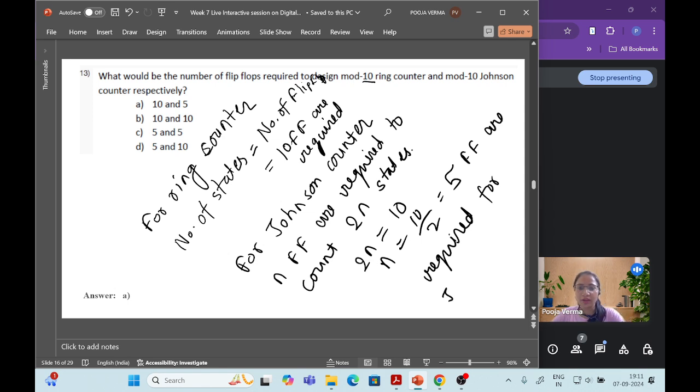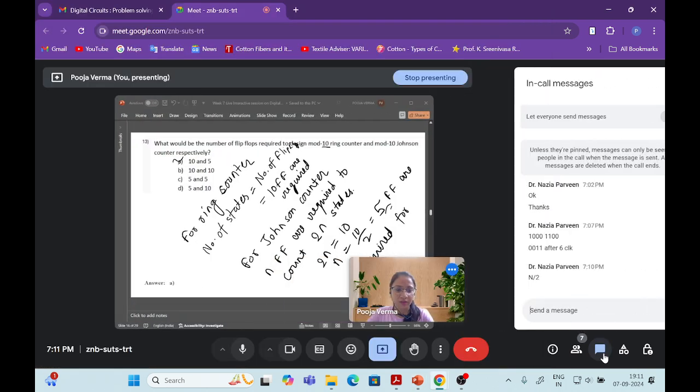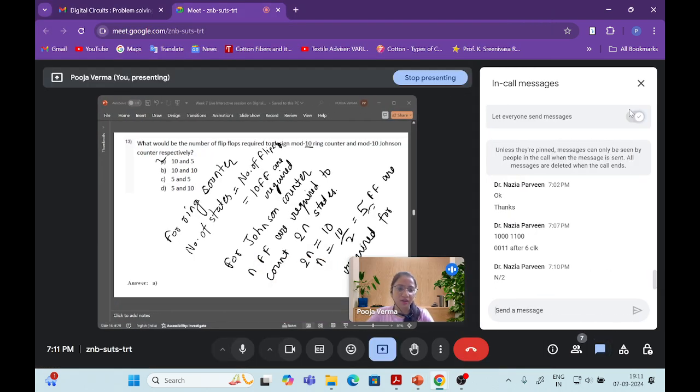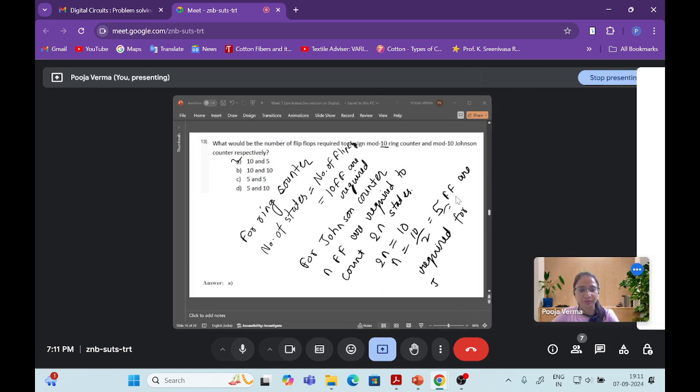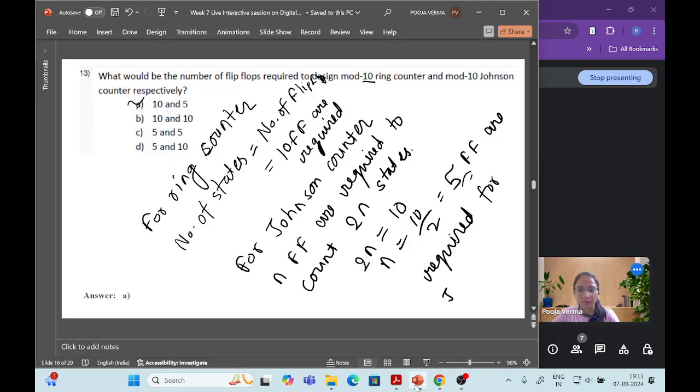Okay, so for ring counter, the 10 flip flops are required, and for Johnson counter, 5 flip flops are required. So option A is the correct answer, 10 and 5. Okay, yeah, correct, n by 2. Okay, so moving to the next question.